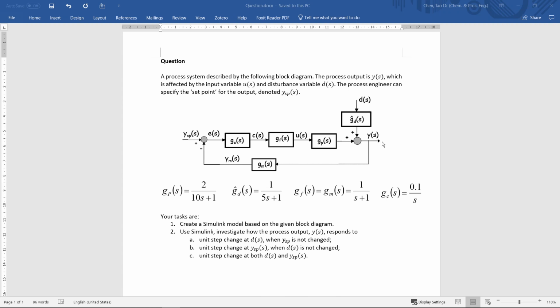And as we understand, for a feedback control system, you measure Y of S, so you link this Y of S, the real process output, through a measurement device, GM of S, that's your usual sensor like a thermocouple or level indicator, etc. You get your measured Ym of S, you compare your Ym of S with your set point YSP, you generate the error, and it is this error, epsilon of S, that determines how you control your process.